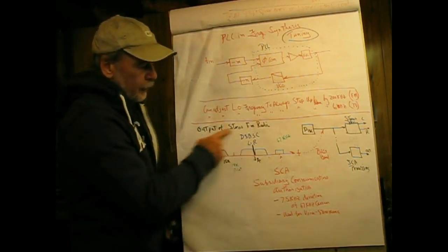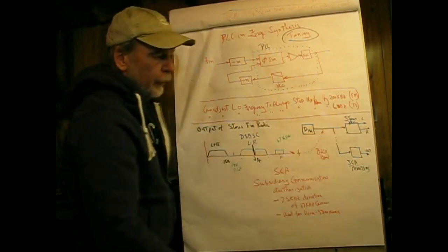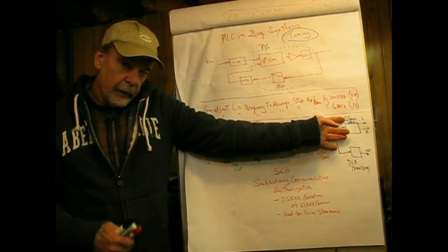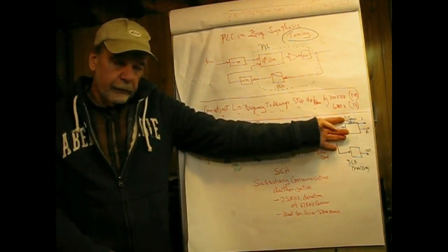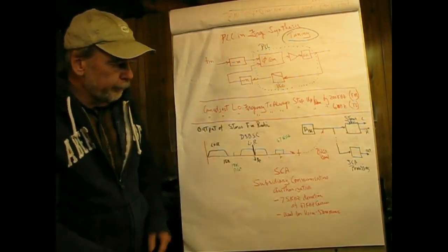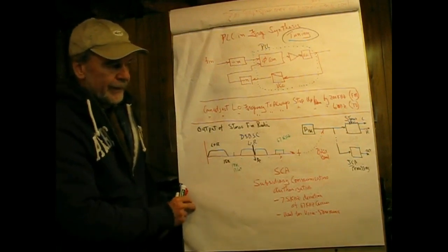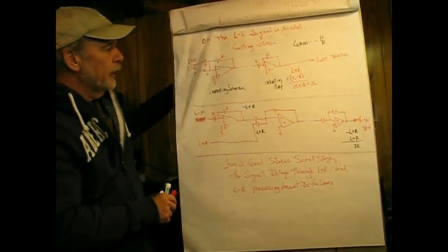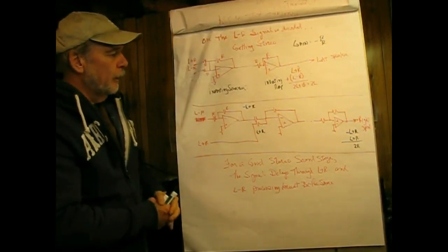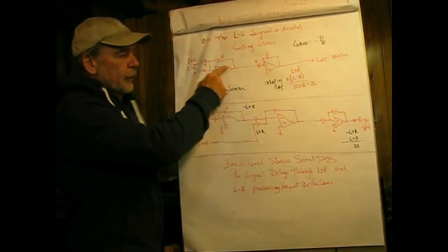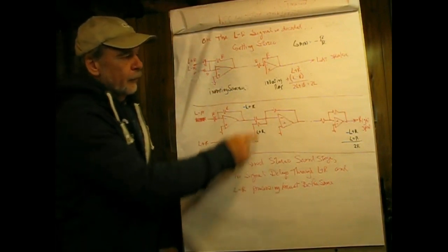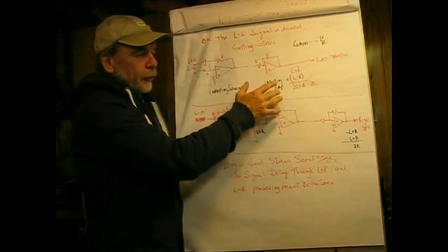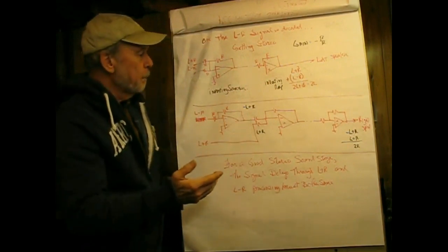So as far as this is concerned, this is fed into the stereo processor, and in the output are going to be audio signals that I've designated as left and right. Now, how complicated can it be to get that? So let's take a look at this. This is an inverting summing amplifier, and this is just an inverting amplifier. I really don't need this, but I'm going to do it because it makes the math nice.